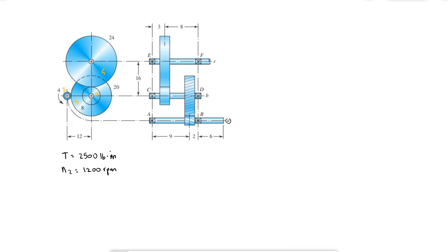Okay, if you look at the side view and front view, I'm gonna label them, you'll notice that shaft A has been moved from its original position. If we were looking at the real front view, you would see that shaft A is behind shaft B, because the side view is the left side of the front view. That's going to be important for the 3D schematics that I'm going to draw.